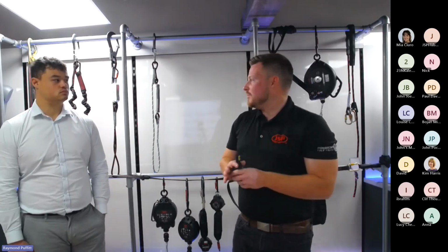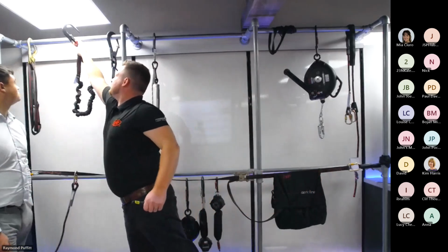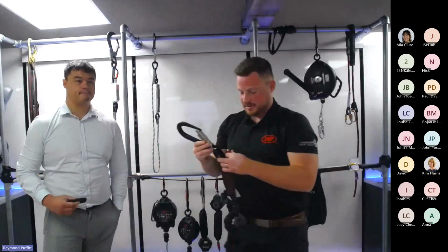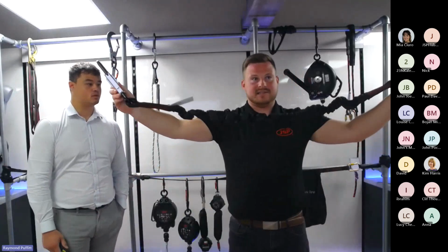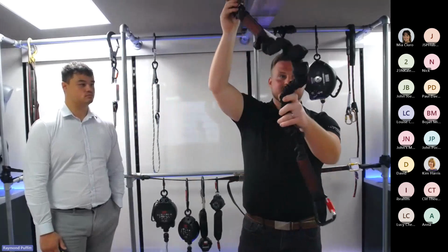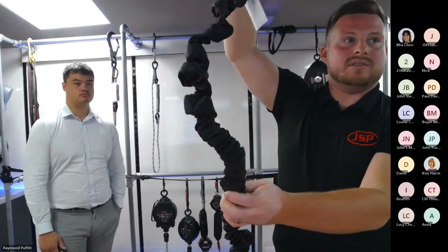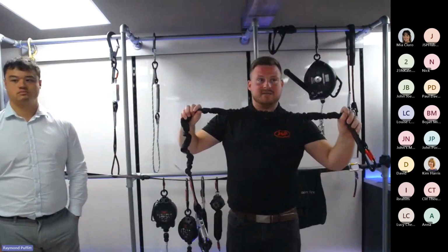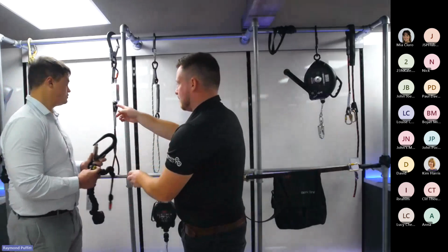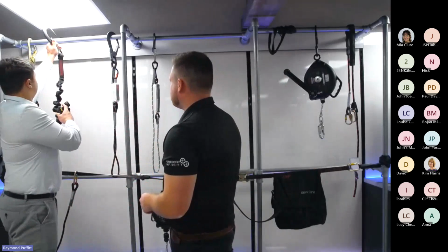Because the standard is so new, there's still a limit on the type of lanyards available. So obviously we all like the elastic style lanyard, the stretchy one. We've all seen these before. With the fall arrest lanyard, the shock pack is inside the webbing here. There's not one currently that's been tested to go over a sharp edge. So again, you'll be taking away a lot of personal preference for what people want to use.